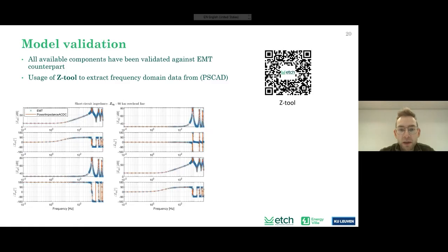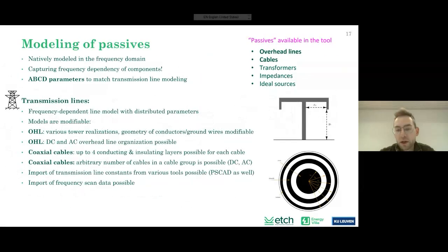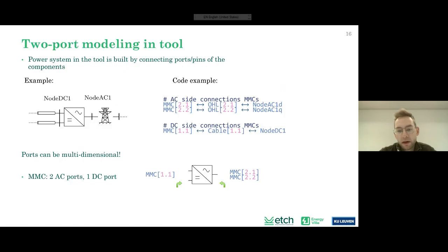That's what we are doing to do the stability analysis and define the loop gain. Yeah, sure. And this is automated again. So yes, it's possible. Given that you have the proper parameters of the lines, you can also just put in lumped parameters and keep it simple. But if you want frequency dependent line parameters, you need to figure out what they might be for these systems. The algorithm is implemented, and it depends on you how you define your system. The algorithm just acts on what you give it, what kind of models you give it.